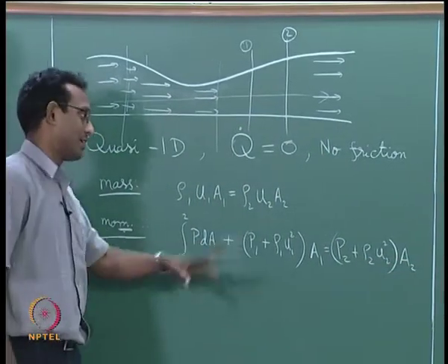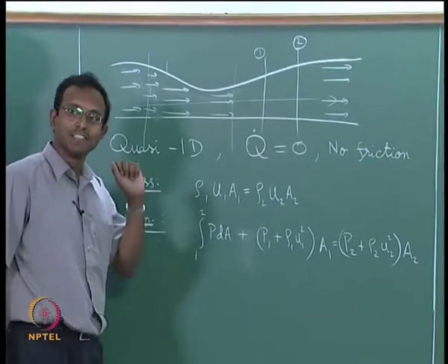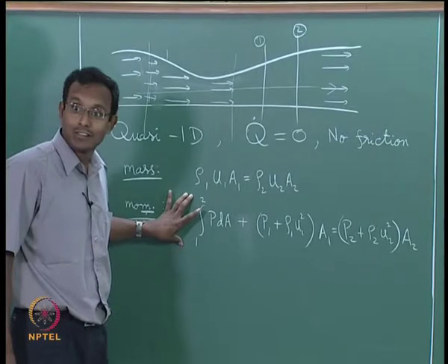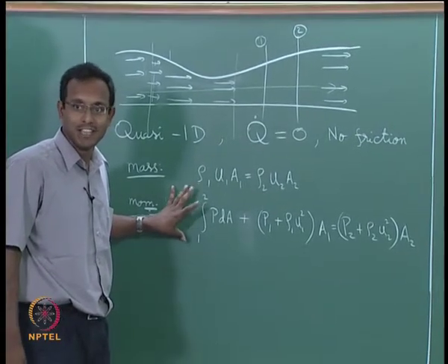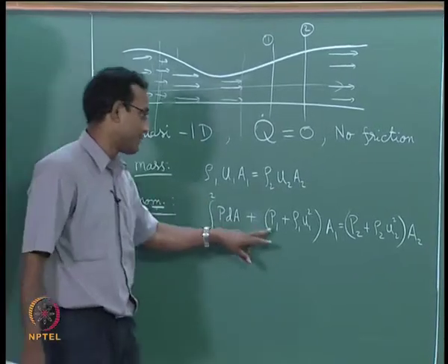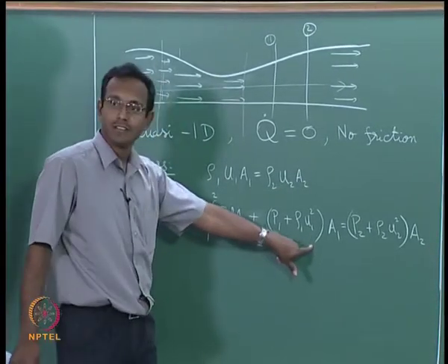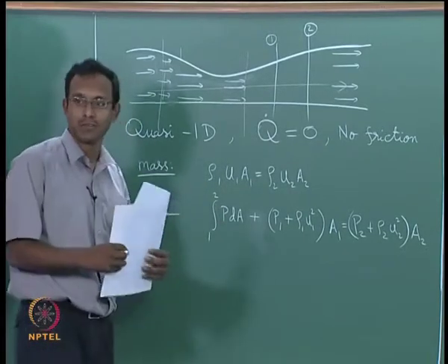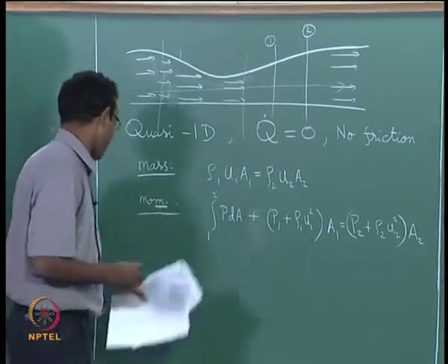It is going to be something like this, and we said that if it is a constant area duct then I can neglect this. Currently I cannot, it is no more a constant area duct, we said its area may be changing. Okay. Initially we said constant area duct, I can say P plus rho u square is a constant, now I cannot do that anymore. Okay. I have to be more careful about which momentum equation I am using. This is the correct one to use.